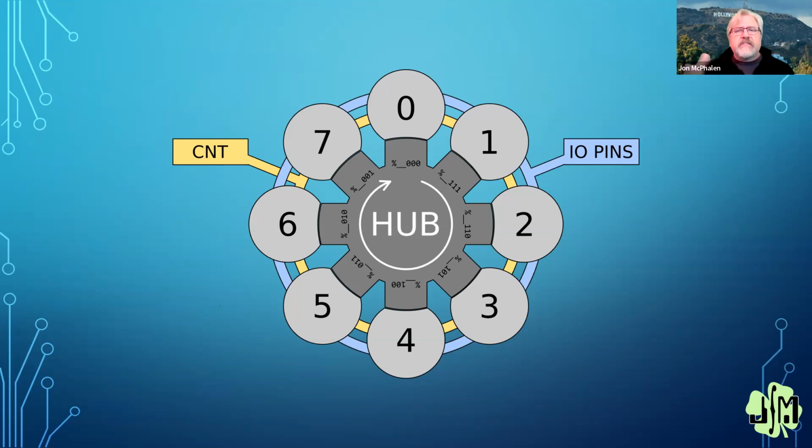The reason for that is several layers. It starts with the processor, of course. In the P1, it takes 4 clock cycles per instruction. The P2 only takes 2. We have a much more efficient instruction set in the P2. In the P1 there are about 70 assembly instructions. In the P2, it's about 350, which looks a little daunting at first.